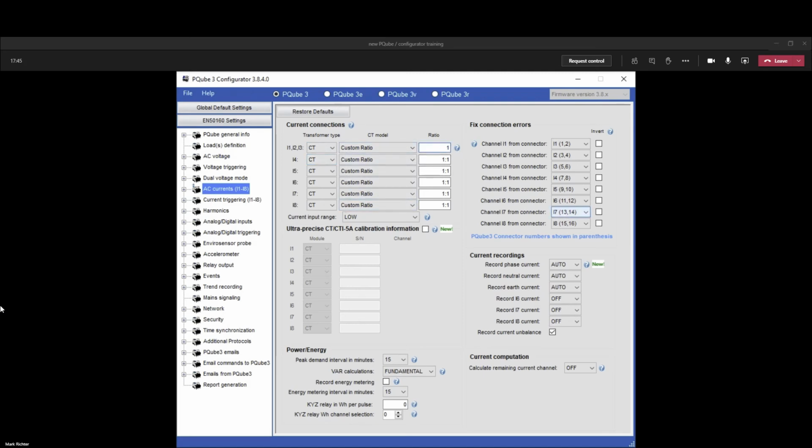So what happens when, installing the meter, someone already has their own existing CTs with a 5 amp secondary? What you'd do is use one of these, which is a 5 amp CT, and it'll be 5 amp to 0.333 volts, right? So you get their ratio, which may be 2000 to 5.